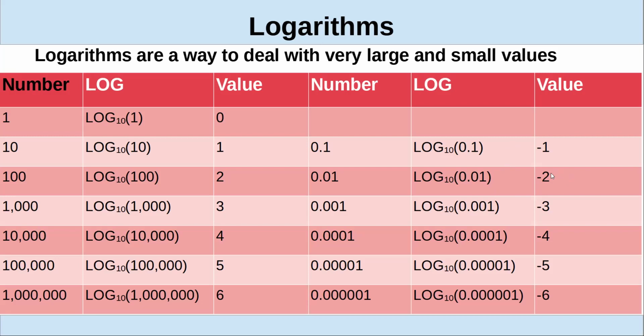When you plot things like filters and amplifiers, they normally chart that, if it's something that's frequency dependent, on a logarithmic scale on the frequency, so that you can cover from 0 to light. Sometimes the amplitude, if it's something like a filter response in particular, will be done in a logarithmic scale, and we'll usually have it in decibels.